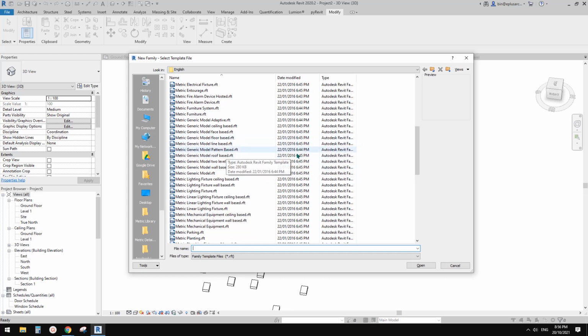You click on two points, and it will place that family, and you can set parameters that change the shape of that family. Also adaptive family. Adaptive family is actually a mass family, and you can create this family using adaptive points. Depending on where you click, it will change.